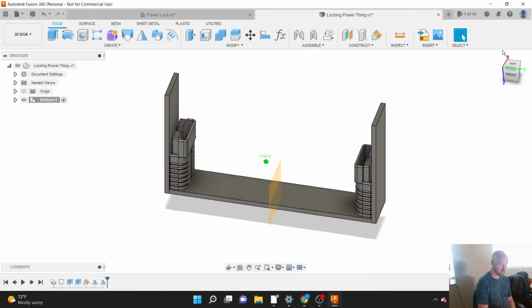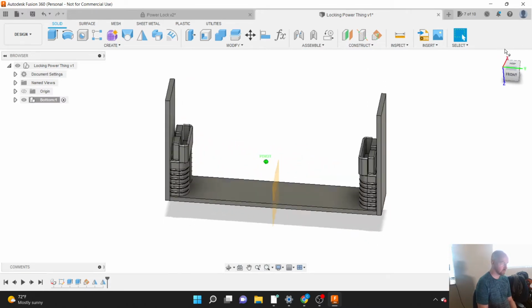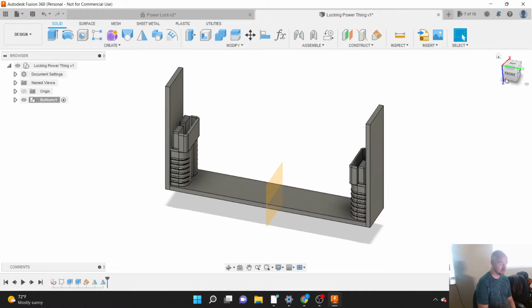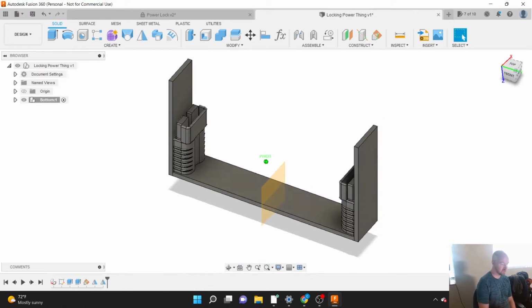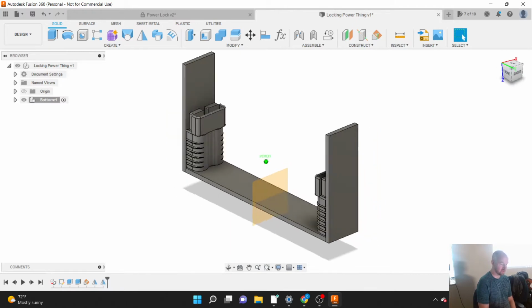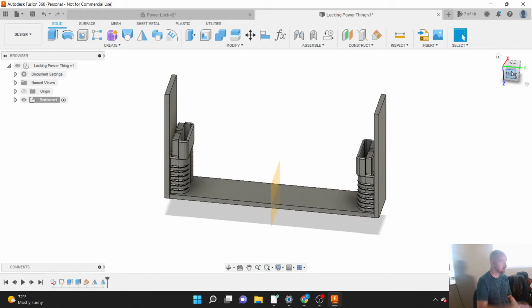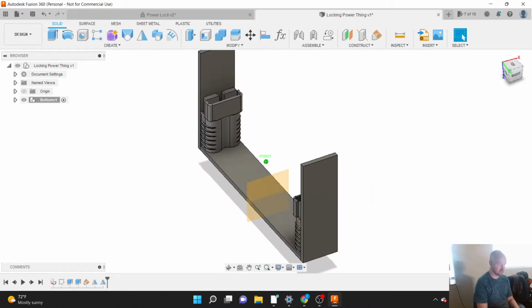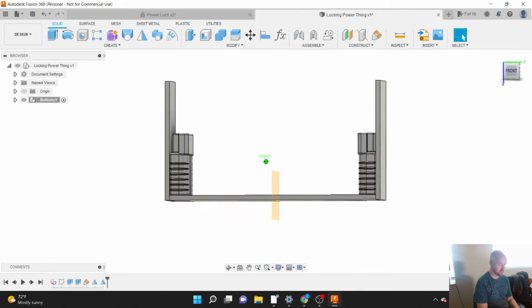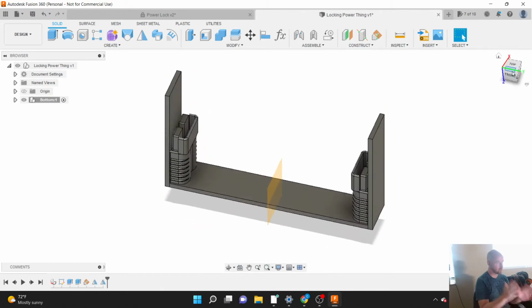Now it's like, I don't know, right side up-ish. It didn't move my X, Y, or Z around, but sometimes that can be useful. It's really easy to rotate an object around the top and bottom poles, like the north and the south poles. It's less easy to rotate things sometimes using the navigation cube if your top and bottom are askewed.